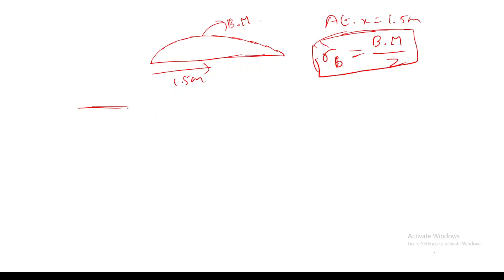For example, here we can see this as the variation. This is a pure bending case. Let's imagine this has 30 megapascal tensile and this has 30 megapascal compressive. Can you say how we can calculate the average bending stress for this cross section? I think it is not possible, it is going to zero.